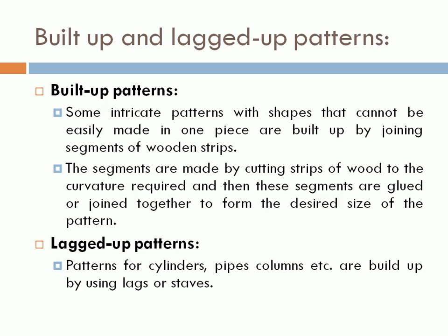Then built up and lugged up patterns. Why is it called built up? Because some intricate patterns with shapes that cannot be easily made in one piece are built up by joining segments of wooden strip, and the segments are made by cutting strips of the wood to the curvature required. Then the segments are glued or joined together to form the desired shape and size.